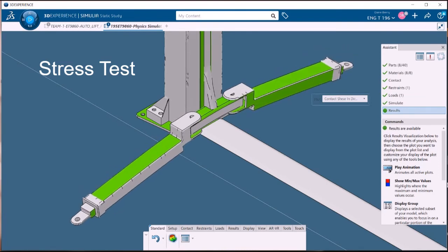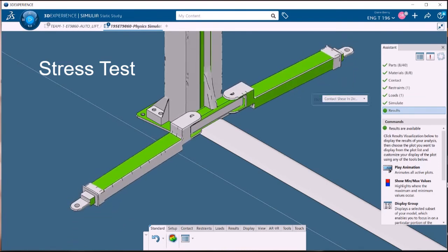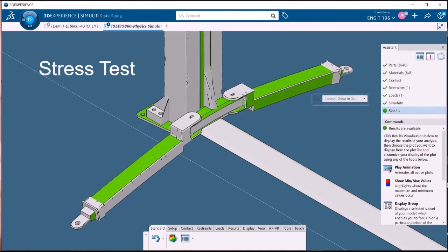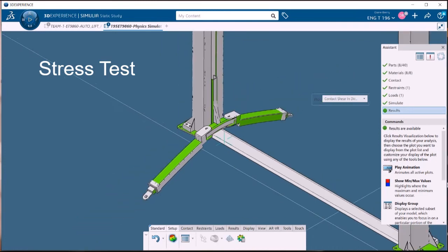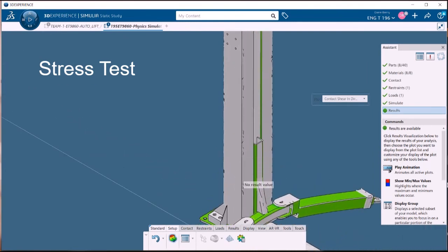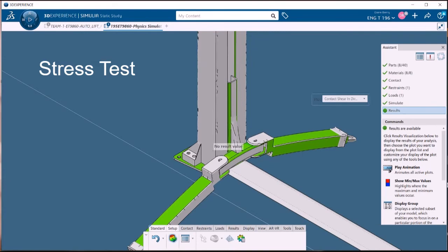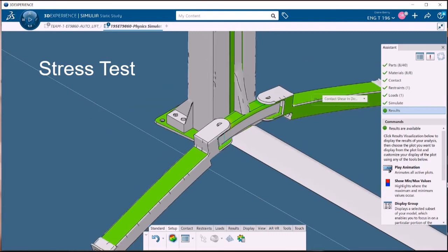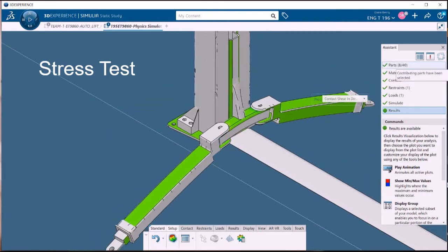One unfortunate thing we ran into with running a stress test simulation in a student model was that we are limited on the size of the model you can run. As the model is converted into a mesh to do the simulation, triangles are computed for each curve, angle, face, whatever you have. And unfortunately, we can have only so many. So we were only able to stress test 8 out of our 40 parts, which, while still interesting and providing a lot of information, unfortunately was not a complete test.